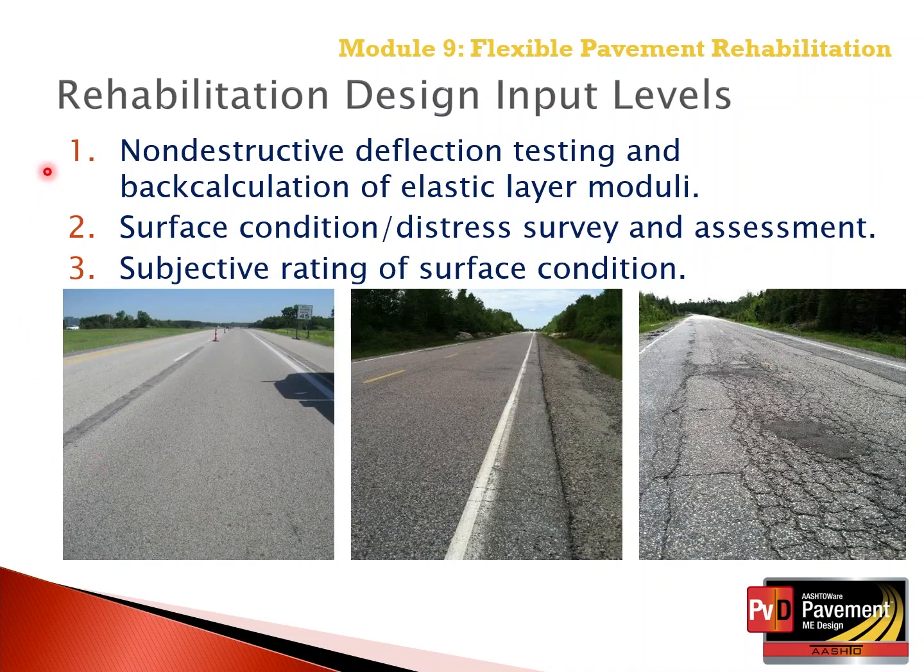Rehab design input level 1 is using non-destructive deflection testing and back calculating the elastic layer moduli, which are entered directly into the Pavement ME design software. That's not to say that the surface condition and distress surveys are not used for rehabilitation input level 1, because they are. But the damage of the existing pavement is based on the non-destructive testing and back calculation of layer moduli.